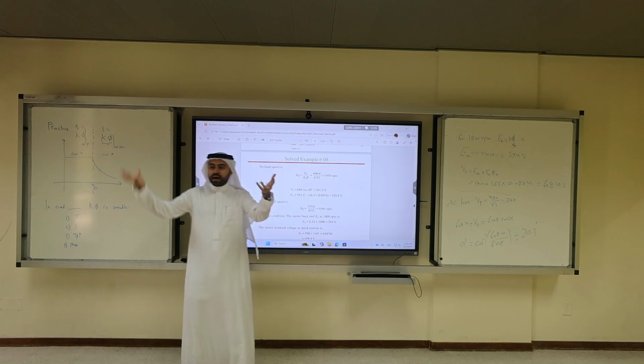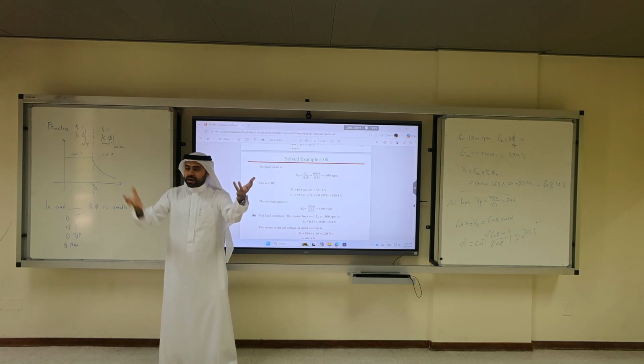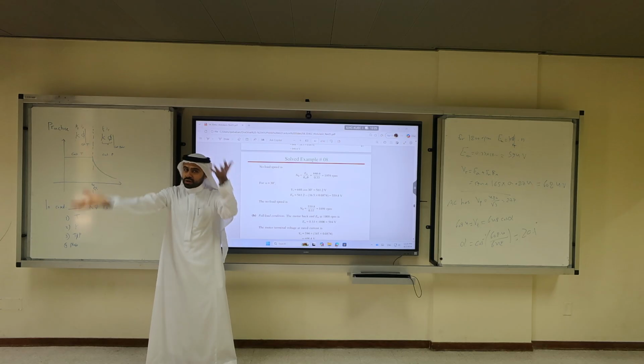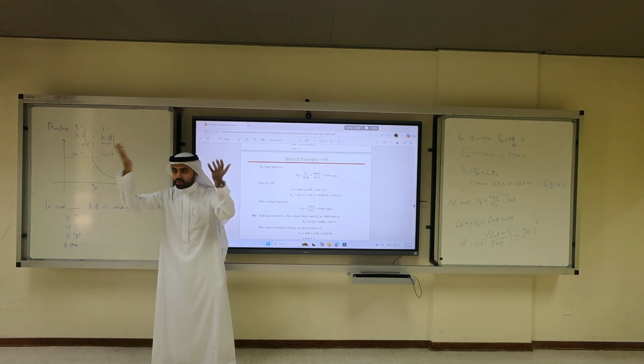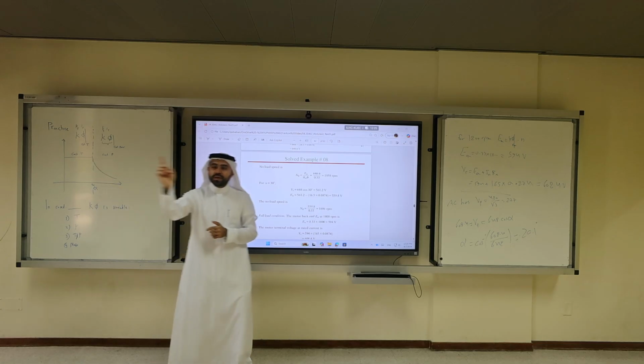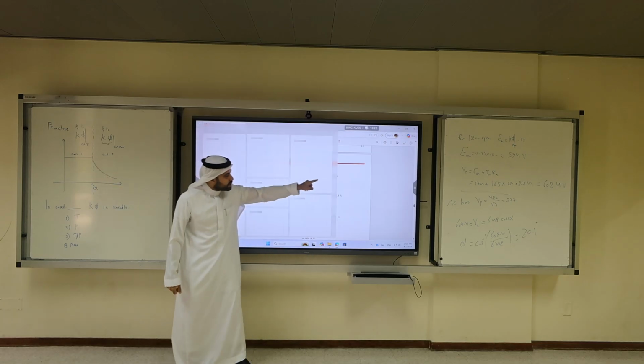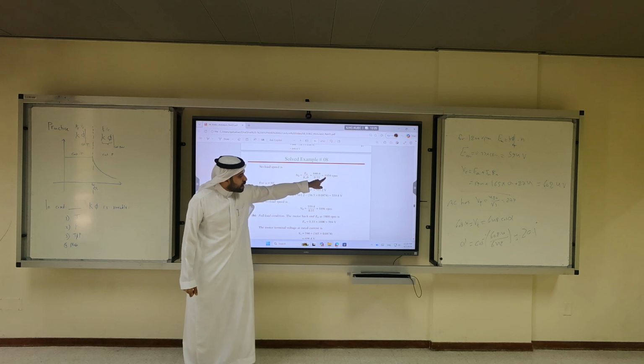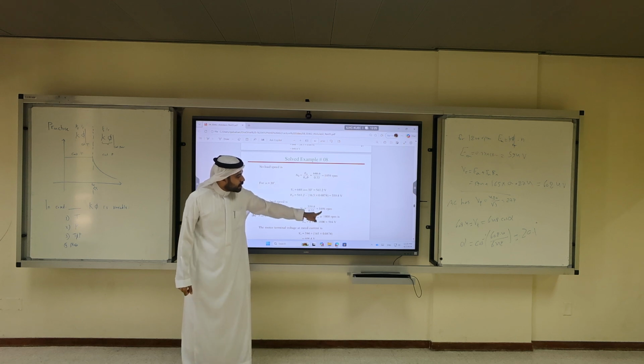So if you change the alpha and you add a load, you have a different combination. So now you have full speed control using the power electronics. Clear? When there is no load, if you change alpha, you will change the speed. And it varies. We tried 1960, we tried 1600, 1700 RPM.